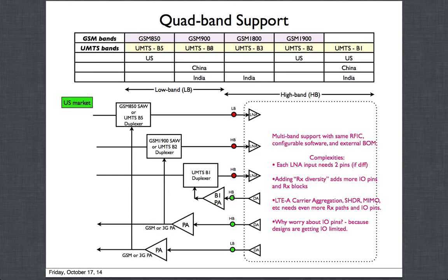Now what is happening is all the circuits have shrunk so much that the blocks take a certain amount of area to fit. But then you also have these I/O pins that have to be there. Whether you have a flip chip type of package technology or wafer scale packaging technology, those package balls are right on top of the die. As the number of package balls and I/Os increases, we find that our circuits and layout have shrunk, and our whole die area has shrunk, but now you know what the problem is? We are not able to fit our I/O pins in it.